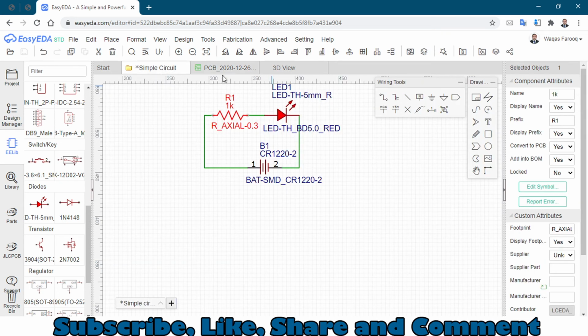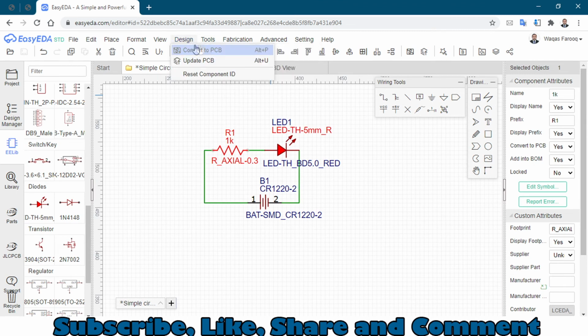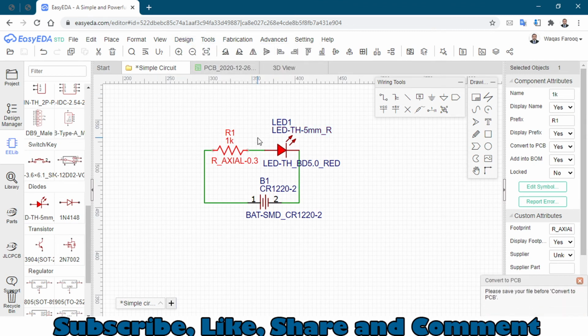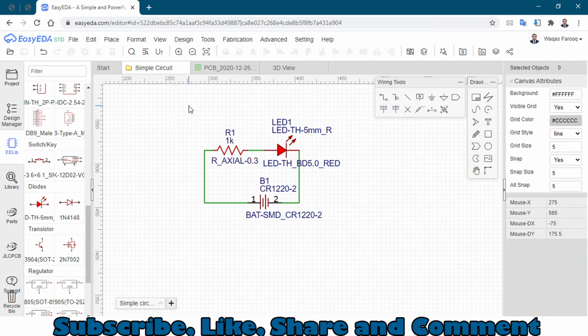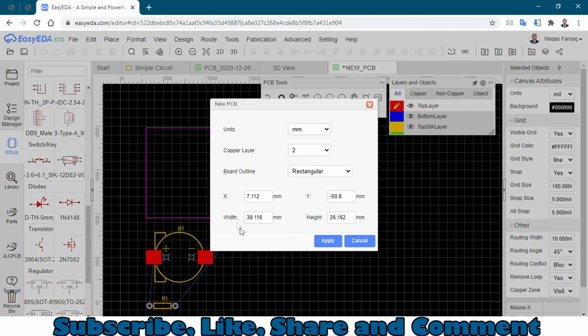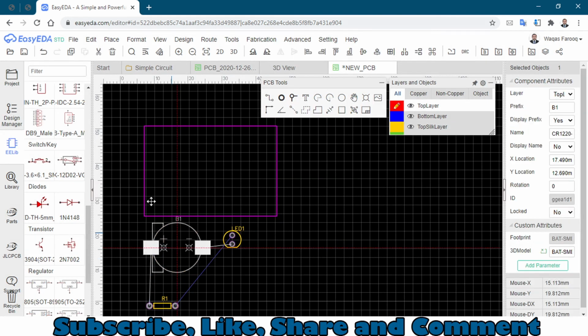We have to convert this also into a PCB layout. Convert to PCB, Control S, and now press Alt P, or you can simply go to the design, and here we have to do the same process and click apply. We have all the components right there.